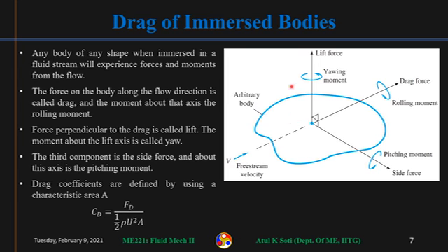So if you have an aerofoil in this 2D plane and flow is coming like this, lift will be in the vertical direction, and drag will be along the flow direction, that you can say x direction. Then pitching motion will be motion about the z axis.